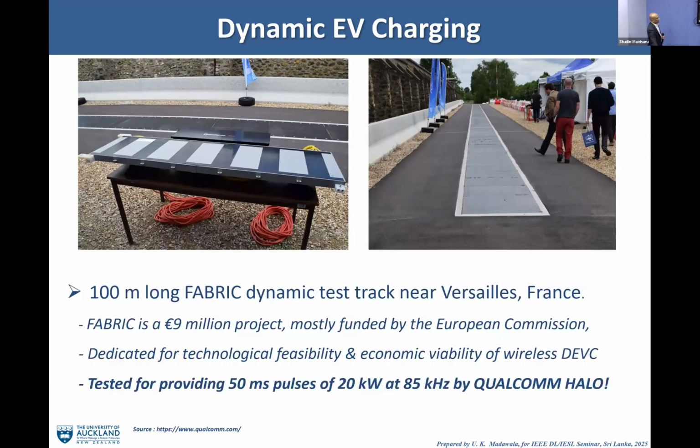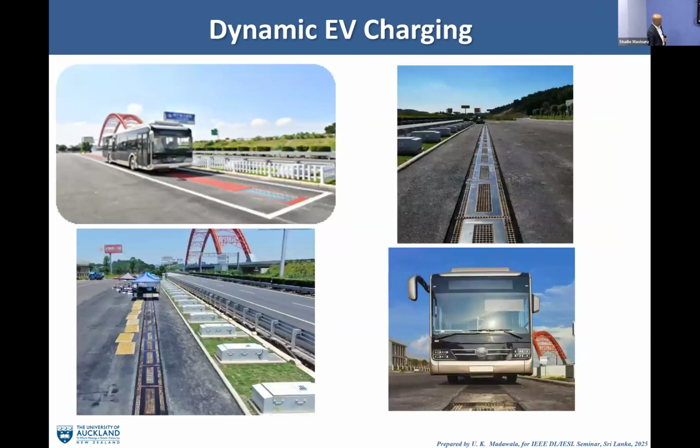So this is being tested. This was done in 2016. And our group, and I'm not actually directly involved in this one, nevertheless, our group was involved with Qualcomm and they tested it in France. And you can see the 50 millisecond pulses of 20 kilowatts generated at 85 kilohertz to charge as the vehicle is moving. I'll show you some of the programs that other countries have already implemented.